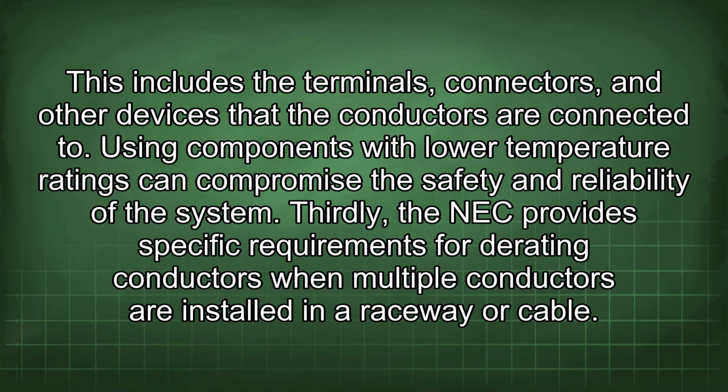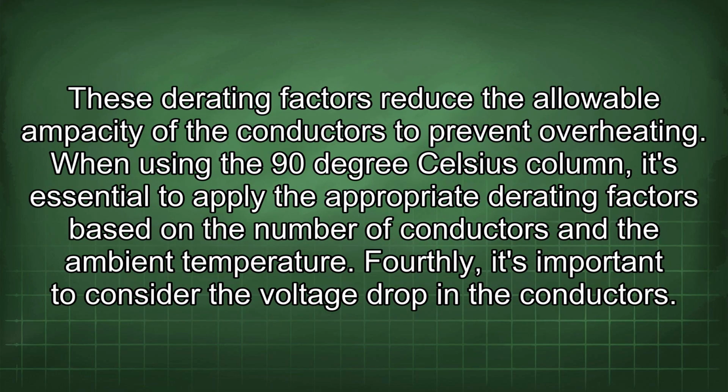Thirdly, the NEC provides specific requirements for derating conductors when multiple conductors are installed in a raceway or cable. These derating factors reduce the allowable ampacity of the conductors to prevent overheating. When using the 90 degrees Celsius column, it's essential to apply the appropriate derating factors based on the number of conductors and the ambient temperature.